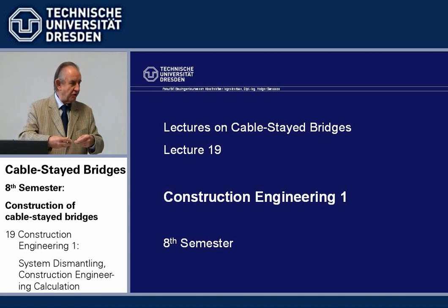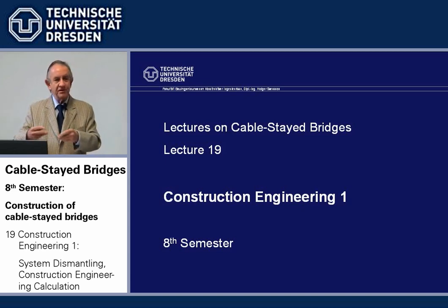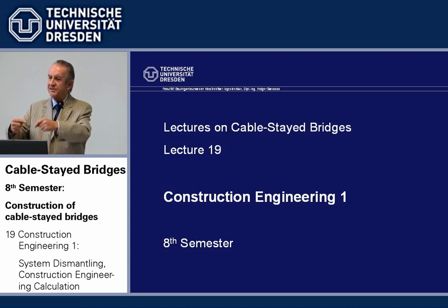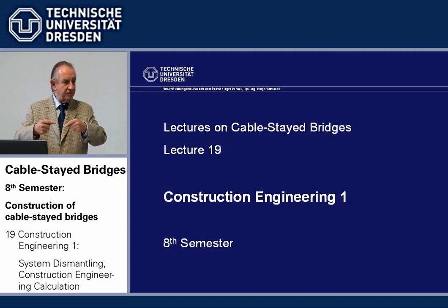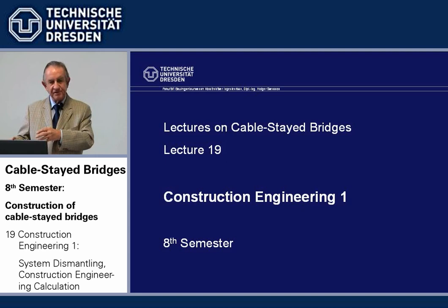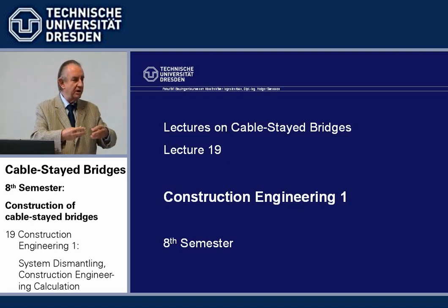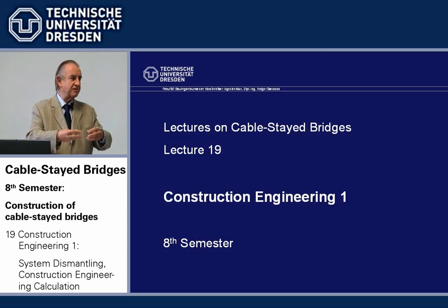So additional cost for strengthening versus more intricate, smaller steps in the construction, which may then permit to go along with the, say, sizing in the final stage. That's always a trade-off. Simple construction methods may require additional strengthening. Additional strengthening may be avoided by using more intricate, smaller steps of construction engineering.